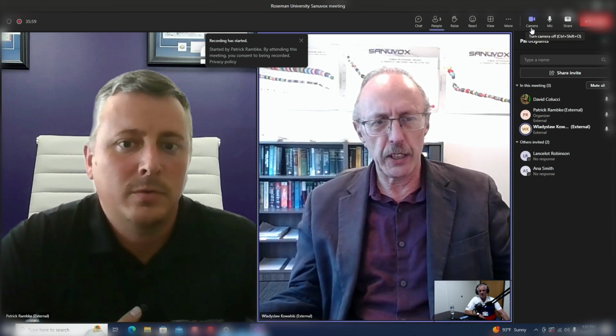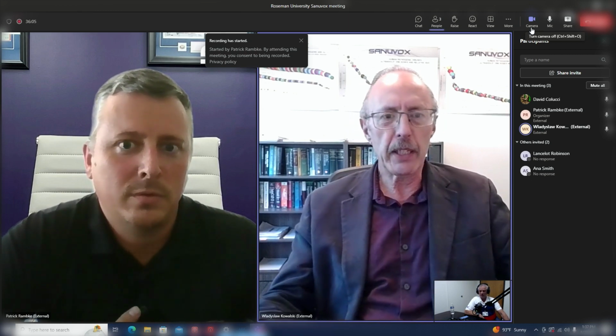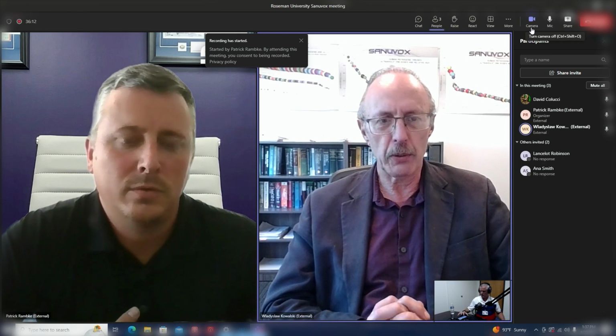UV can take out a large number of VOCs and odors. We've been discovering that again and again. It can be chemically reactive with certain VOCs. UVC lamps, low pressure lamps that produce no ozone, are capable of inactivating a wide variety of chemical compounds. But medium pressure lamps or vacuum UV lamps produce ozone, and the ozone has a superior effect. It greatly reduces odors and VOCs, but you can't have residual ozone.